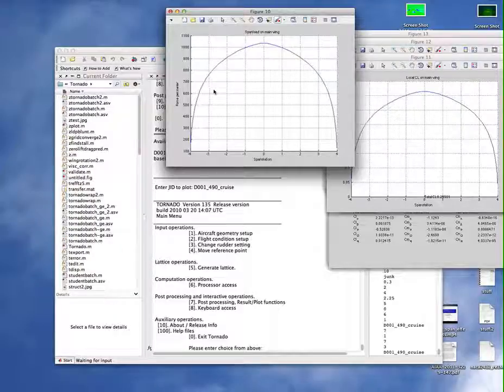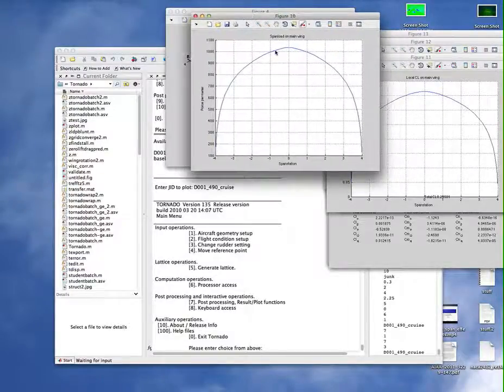So by taking the load away, the downwash is more constant. I wish this reported that. The downwash is more constant. We have less induced drag, and also reduce the bending moment, which means if we're given a beam, essentially, we can have a little bit higher aspect ratio, which means we can get even more benefit. So twist can be good.